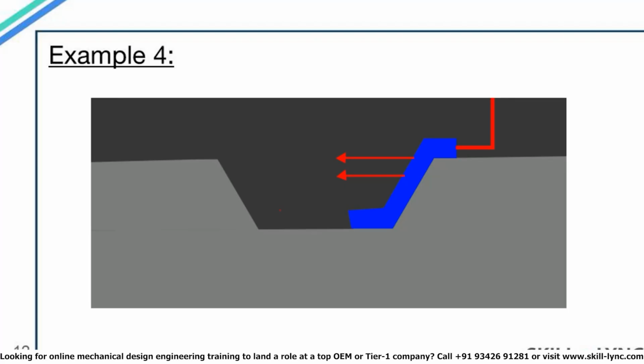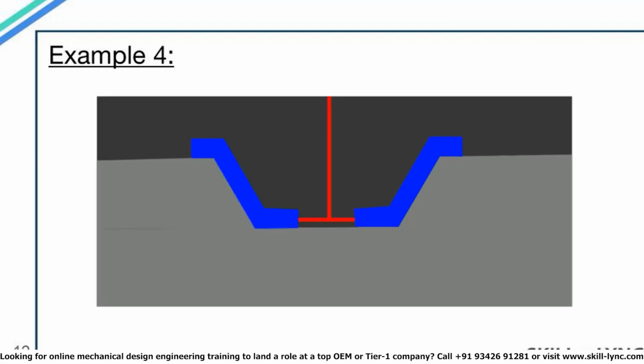So this locking issue would only happen if we are molding only one component. If we were molding two components together, then the mold block would look something like this. So here we don't have to worry about the blocks moving in the horizontal direction. The inlet of the molten material will happen from the center, which is shown in red in the diagram, and the forces on both the sides will be balanced.